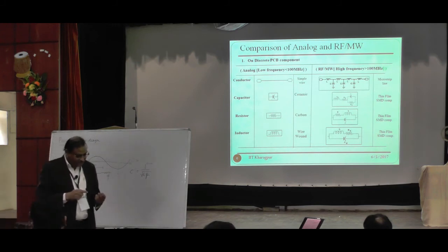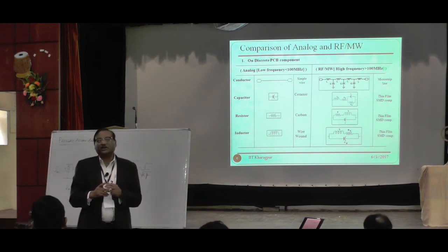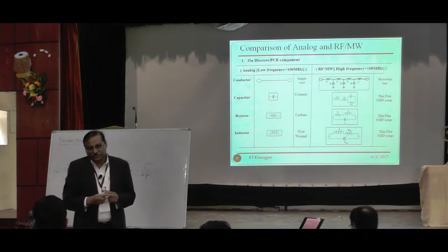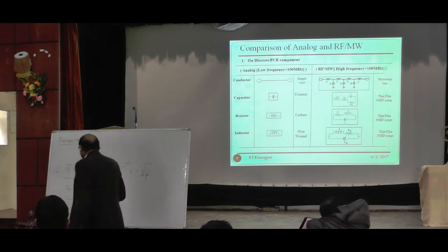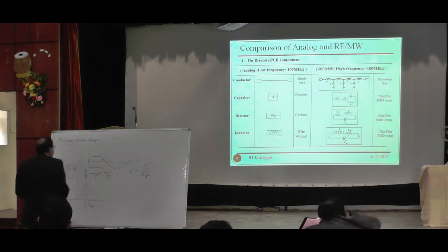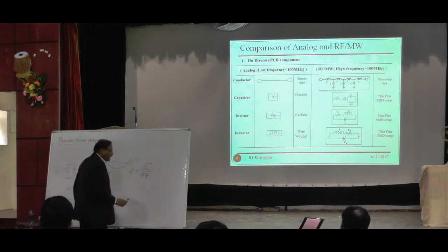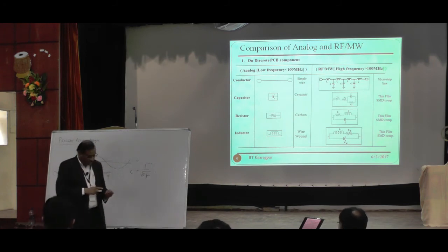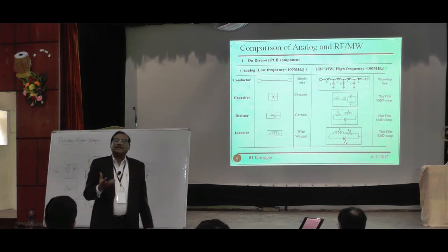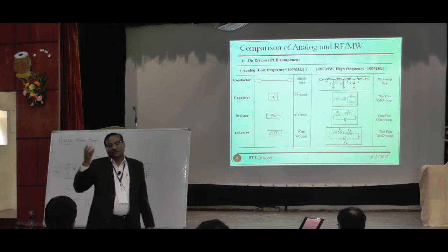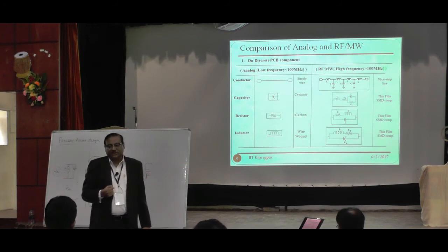At 65 gigahertz, first of all, the cutoff frequency of your transistors should be as high as possible. And then I will go to the silicon process probably to be better for you, but I will just tell you that there is a special substrate. A normally high resistivity substrate is used to improve the cutoff frequency of the transistors.